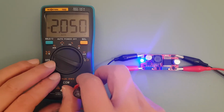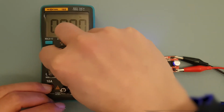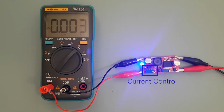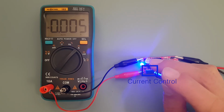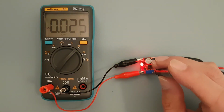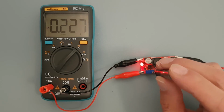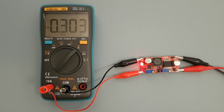Next, put the multimeter in the current measurement mode, and move the red terminal to the current measurement position. You can see there is almost no current flowing because the current control potentiometer was initially set to a minimum. Now, let's rotate the current control potentiometer clockwise so that it is 300 mA. We are now ready to connect the LED.